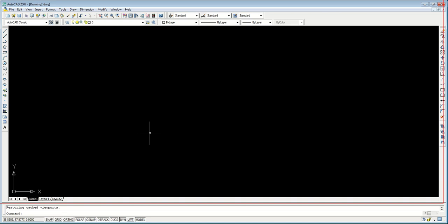Okay, so first we want to see how to draw a line. By clicking on the line tool, it will give you, if you look at the window behind the big cursor, a prompt: specify first point. Move by your mouse; don't use a touchpad, because it will make it hard to draw. If you want to draw a line, you have to specify 2 points for the line: the beginning of the line and the end of the line.